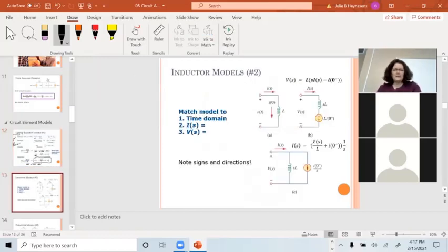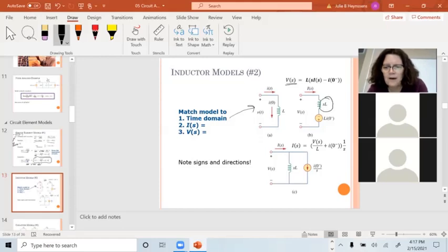Okay, if I have an inductor in the time domain, I have something that looks like this. And I put the equations on these slides too to make them make more sense. I of S, let's start out with the easy one. V of S, I'm modeling as two pieces. One is SL I of S. So this is like an inductor with an impedance value of SL, takes care of this first term.